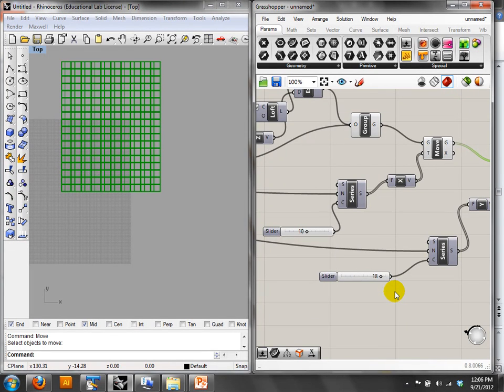And you can take the stuff that I just showed you, and turn some of them off, distribute them into groups. You can do more than 2 cull patterns, like this whole kind of checker thing that I've shown you. If you get the pattern right with the true falses, you could do any number of things you want. You could also do true, true, false, and then do false, false, true, right? So don't get stuck with that pattern. What if you have 3 things that you're distributing along this in different patterns?